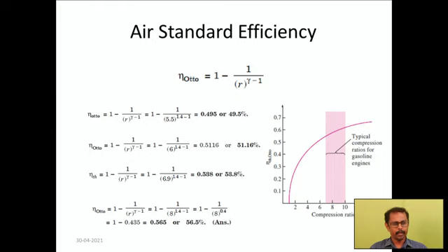And in the next equation the compression ratio is changed to 6, and now we can see the efficiency of the Otto cycle, which is 51.16%. Now we have raised the compression ratio to 6.9. The efficiency is derived as 53.8%. And for another compression ratio, 8, the efficiency of the Otto cycle is 56.5%. From these values we could understand that the efficiency increases while increasing the compression ratio.